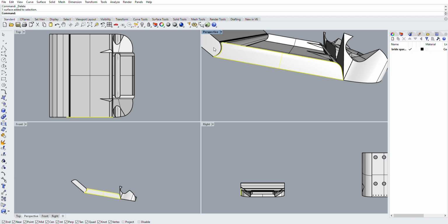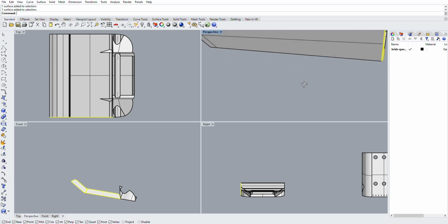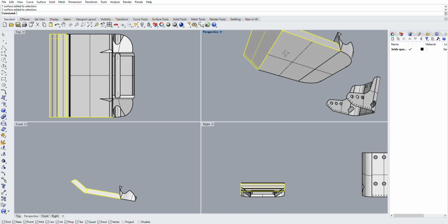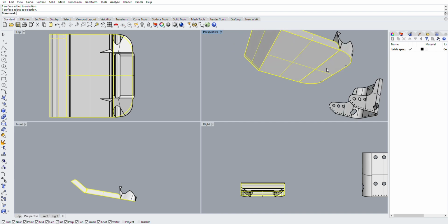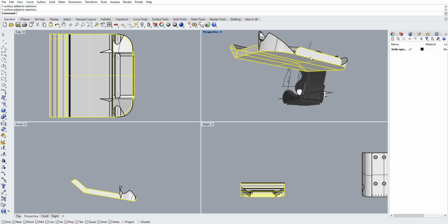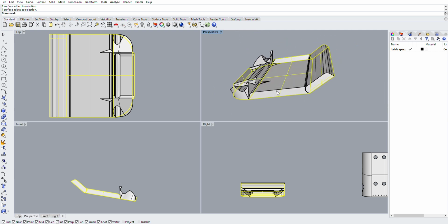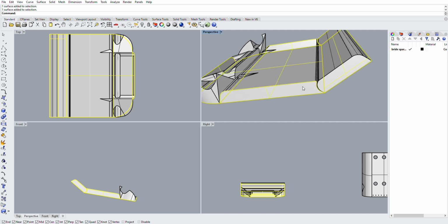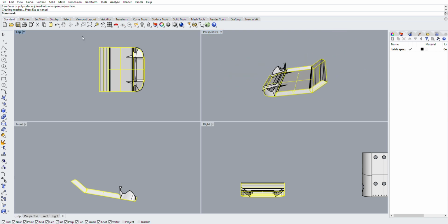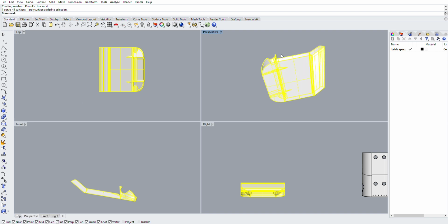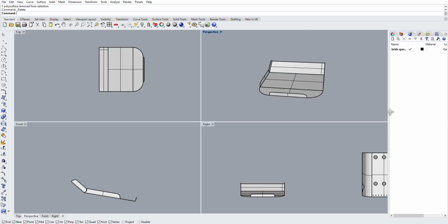So instead of that, I'm just going to grab the outer faces of my flange, the two side flanges that fold up, the pieces that make up the base, the back flange, the other two sides, and I'm going to join all of those together. All you do is type join once they're selected, hit enter, and they become one piece. And now I can select everything, then holding shift or control, deselect that, and it gives me my base piece.